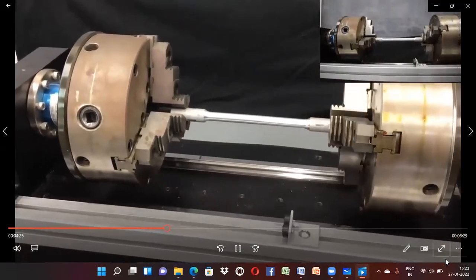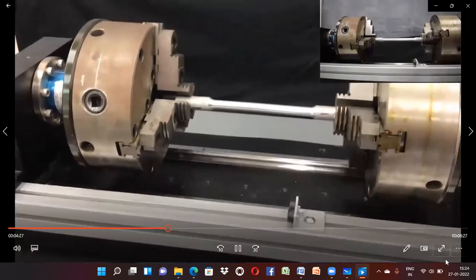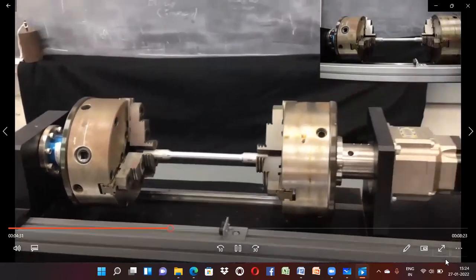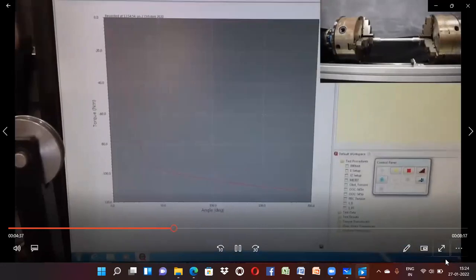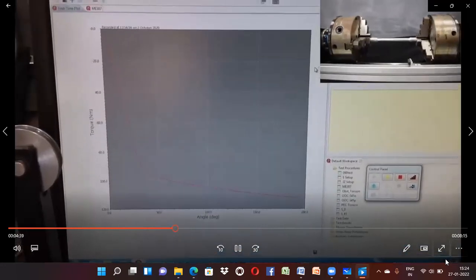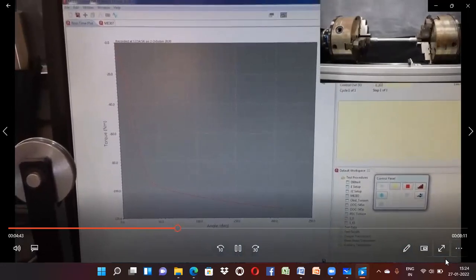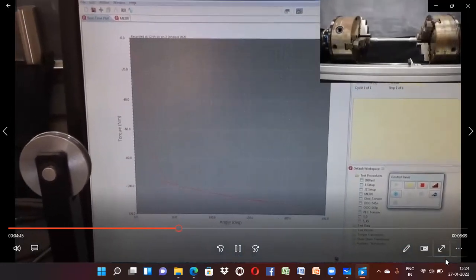And you can see this thing is rotating at almost one full revolution per minute. So it's pretty high strain rate as this thing twists. And if you look down there, I can barely read that. It looks like we've hit 200 degrees of twist already in just under a minute, so that about makes sense. And we can see that it's already starting to level off.